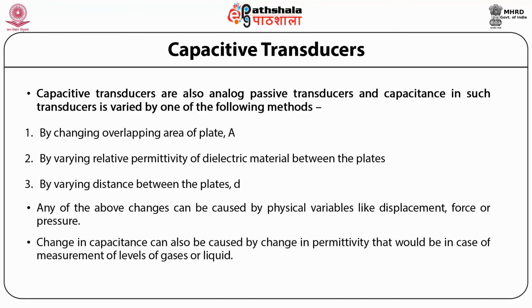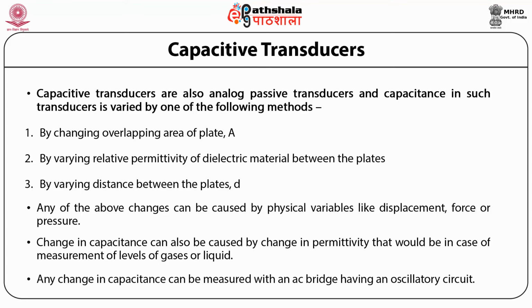Change in capacitance is also caused by change in permittivity, as in the case of measurements of levels of gases or liquids. Any change in the capacitance can be measured with an AC bridge having an oscillatory circuit.